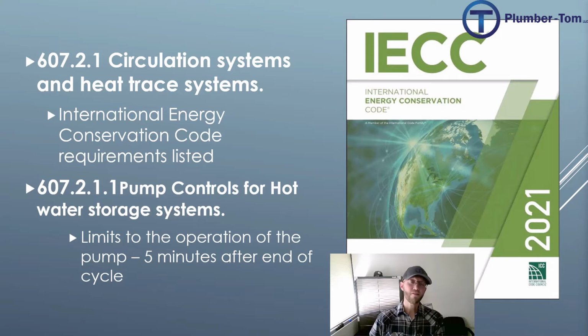607.2.1 gives us information about the pump controls for hot water storage recirculation systems. So here's how it works. When the water heater heats, it goes through a cycle. At the beginning of that cycle, the pump can come on and it can push water. But the pump should stop within 5 minutes after the water heater stops heating, so that that pump is not constantly running. All pumps nowadays that are installed should not be running constantly.